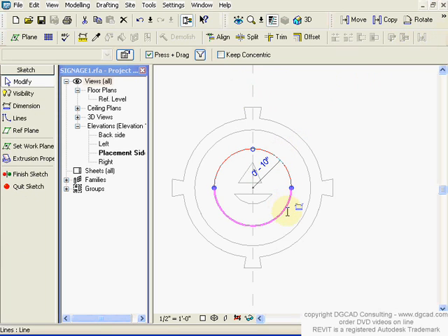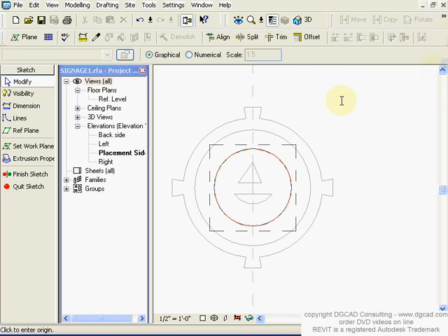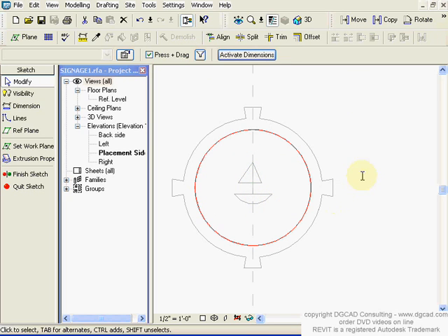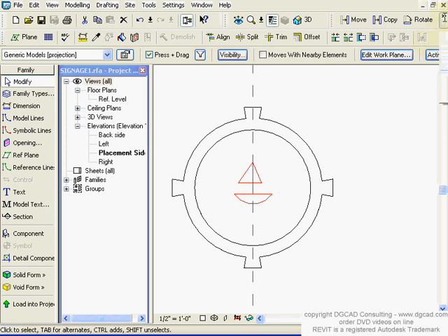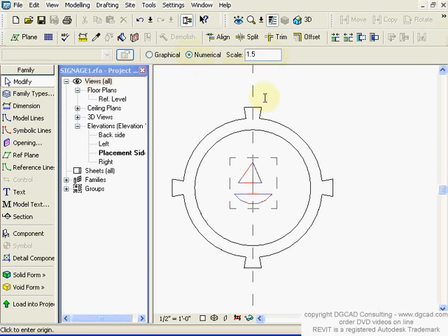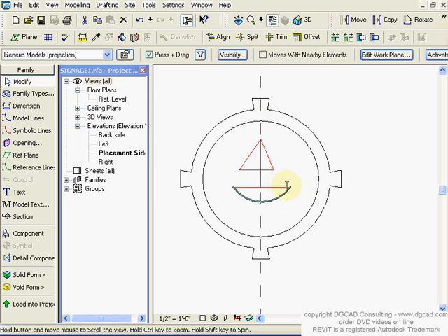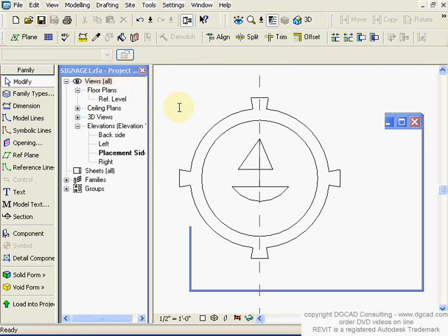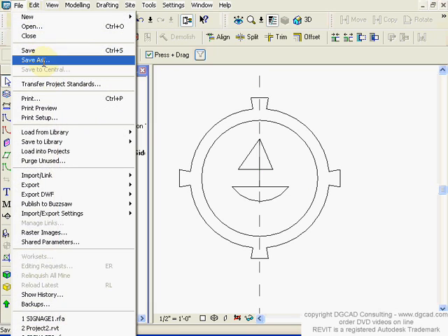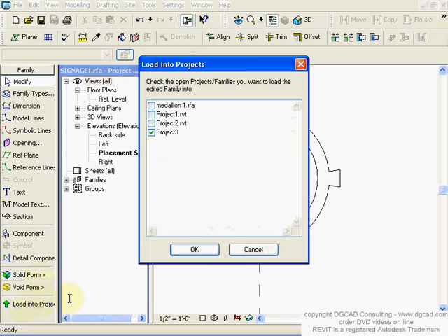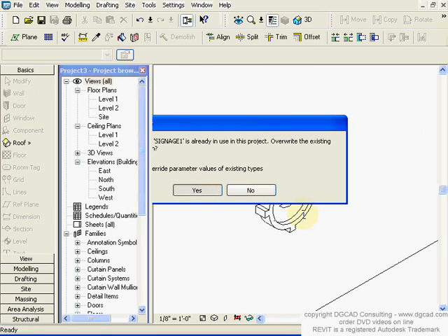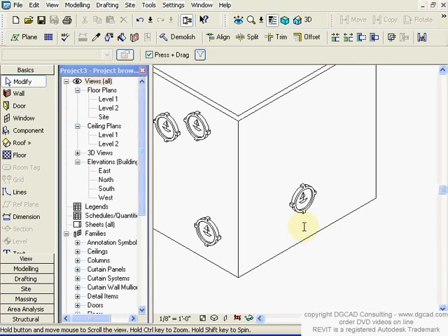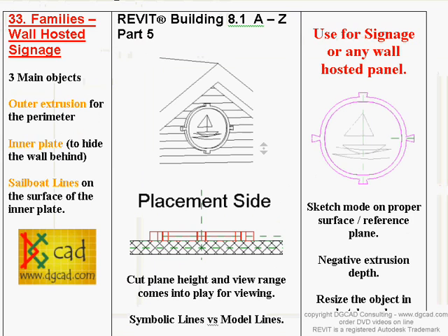and then I can now go click on here. Again, I can go into edit, and then I can click on these two objects and go to my resize, numerically 1.5 based on here. That's out to there. Finish the sketch. Okay, now these are the ones inside of here. Yes, I can resize it, numerical 1.5 based on the center of that, probably there. Okay, then I could take this and I could save it, or do a save as probably instead to make a different one. Okay, and then in this case I've done a save, so it's going to update all the existing ones, so they're all going to get a little bit bigger based on that size.